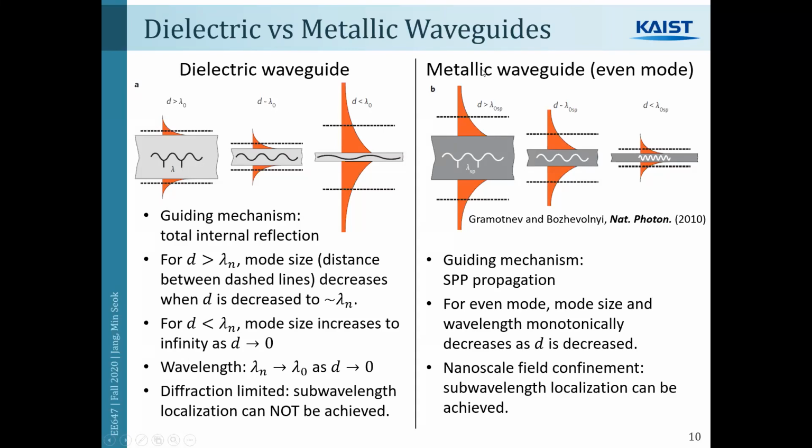And of course, as we said earlier, the metallic waveguide also has a disadvantage, and that disadvantage is loss. In a dielectric waveguide, the mode can propagate a very long distance without suffering from loss, but in a metallic waveguide you can only propagate a few tens of microns, definitely less than millimeter size. That is one of the biggest obstacles in utilizing metallic waveguides. But at this cost, you get high confinement, so metallic waveguides are useful, not always, but in cases when you require extreme mode confinement.